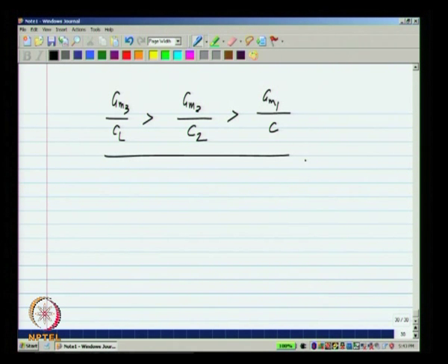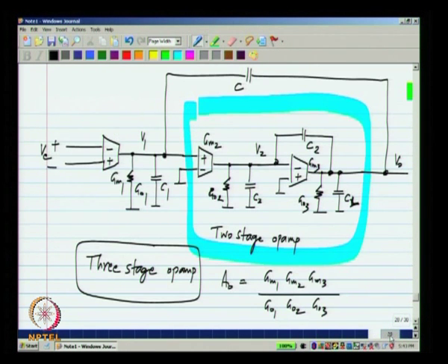So, this also points to some constraints. Like I said, this is only an approximate description, because now the transfer function of this can be quite complicated. You will have a third order denominator and also you will have two zeros because of these parallel paths through the capacitors and so on. It is not very easy to figure out where those zeros are. Intuitively you can do it analytically and then do it quite easily,